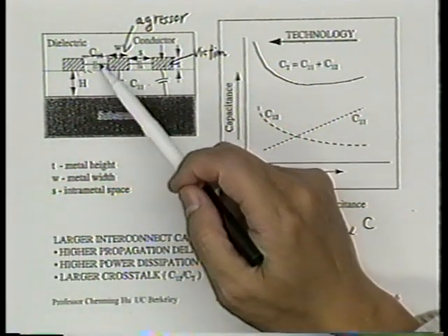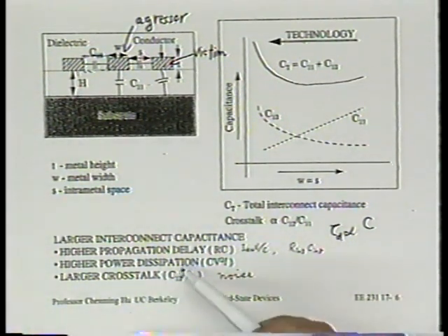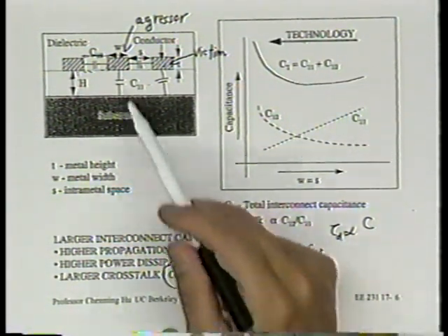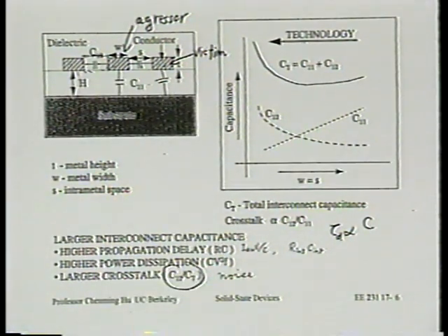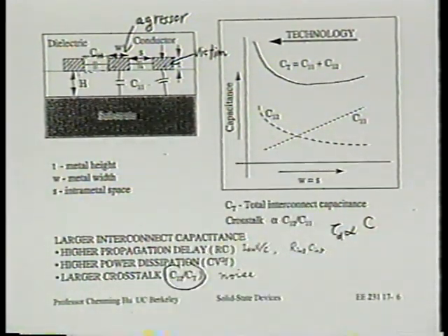That way we can minimize C12, but not change C11 too much. You see that? And this is because of the realization that C11 actually helps a little bit in terms of noise sometimes. Now, if that trade-off is not there, then the technologists are going to develop a technology that's all low K, for example. So this information is transferred back and forth between technologists and designers.